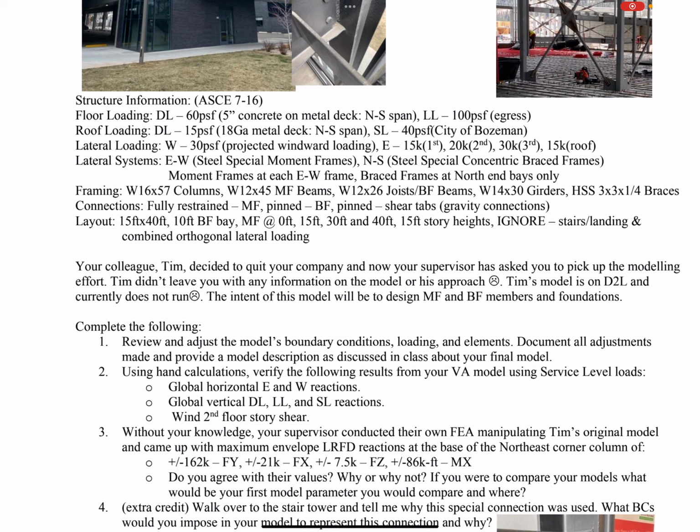What else? What are we at now? Layout, so it's 15 feet wide, it's 40 feet long. We have a 10-foot brace frame bay at the end of our building. The moment frames, well, we have a frame at 0 feet, 15 feet, 30 feet, and 40 feet, right? So 30 to 40, obviously that's where our brace frame bay is, 'cause it's sitting between these two frames in that end of our building.